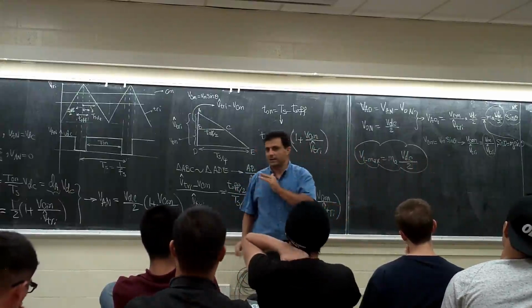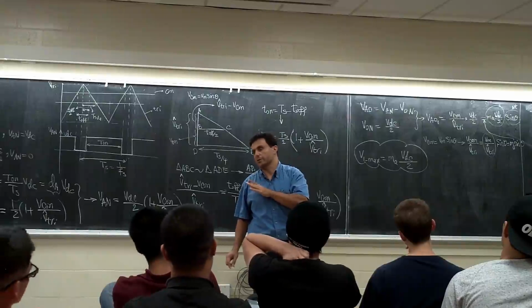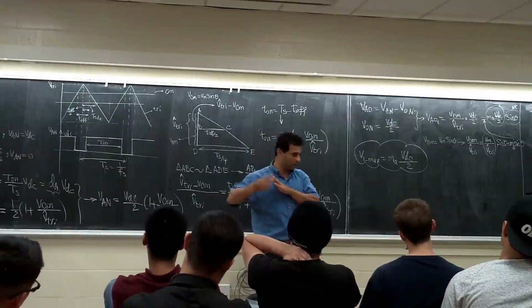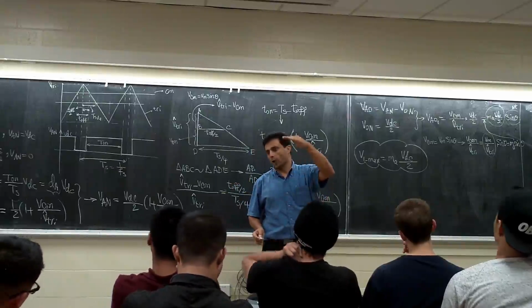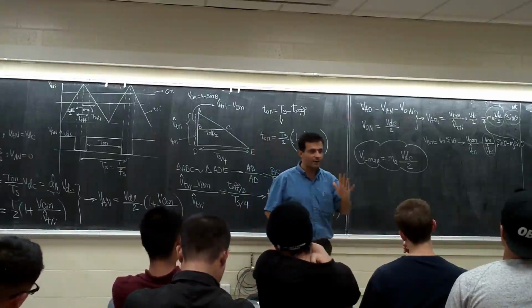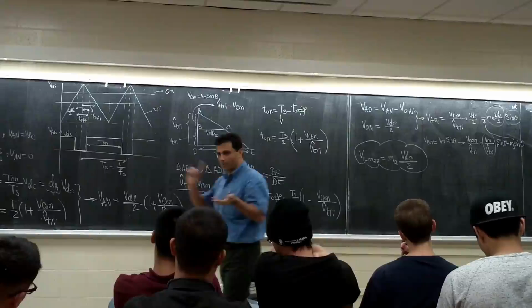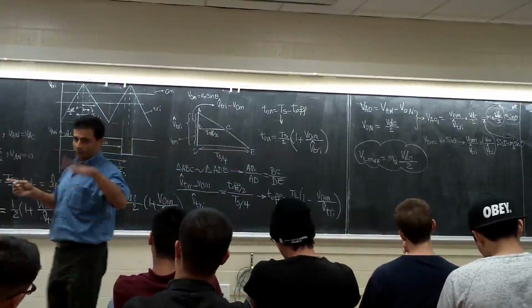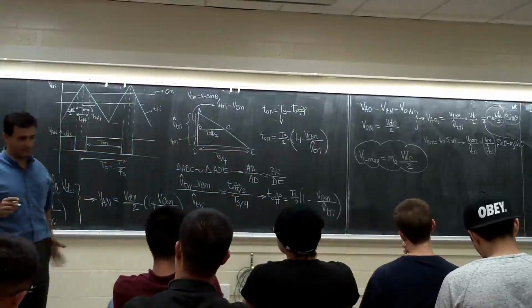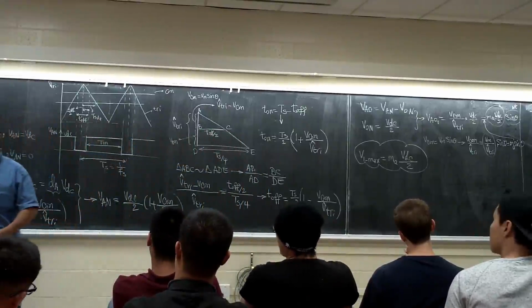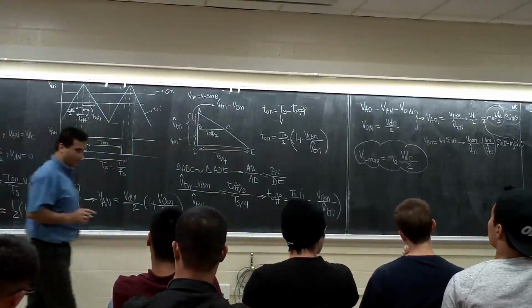So basically, say, okay, the minimum value for MA is 0.7, for example, based on what my VDC is. And it can go up to 1. But up to 1 is a control parameter. There are some of the things happening in the circuit, you have to change MA. We'll talk about that one later. Your project is going to be exactly calculating this MA, the control loop for the three-phase inverter.